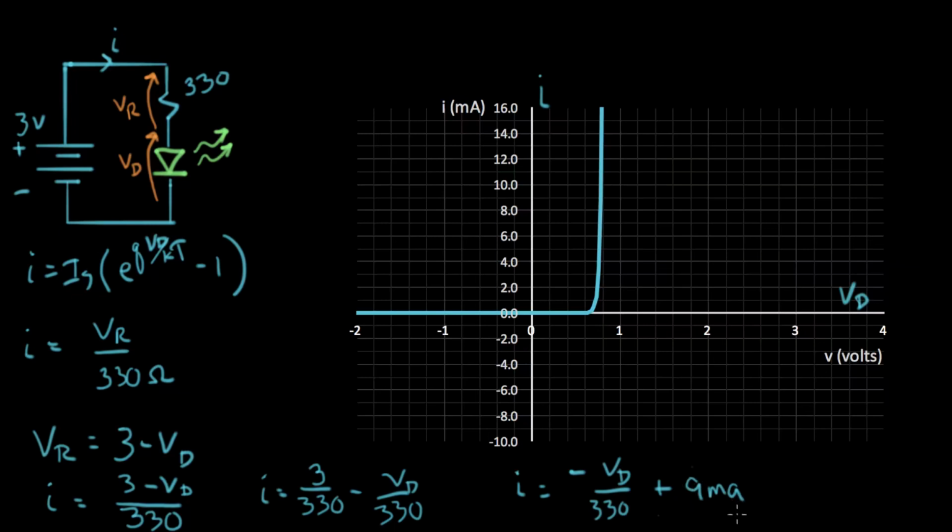So let's see if we can plot this line. This is actually called a load line. That's just a nickname for this kind of expression that you get when you have a resistor connected to a fixed power supply above, and the resistor is hanging down from it. You get this characteristic equation of a line that has a negative slope, which is really distinctive. Now, it's a line, so all we have to do is find 2 points that solve the line, and then we'll be able to draw the line.